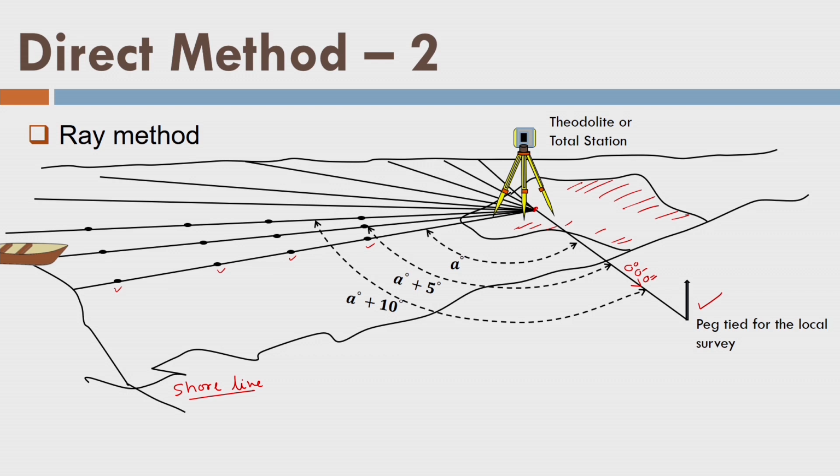Now you are measuring the XY position with the help of the float line. I can use any instrument for sounding. It is not a pseudo 3D survey. It is a perfect 3D survey where we are measuring X and Y position, and we are measuring the sounding position. So 3D data is collected always simultaneously. Although we have separated the vertical and horizontal survey here, still we are measuring the 3 data simultaneously.